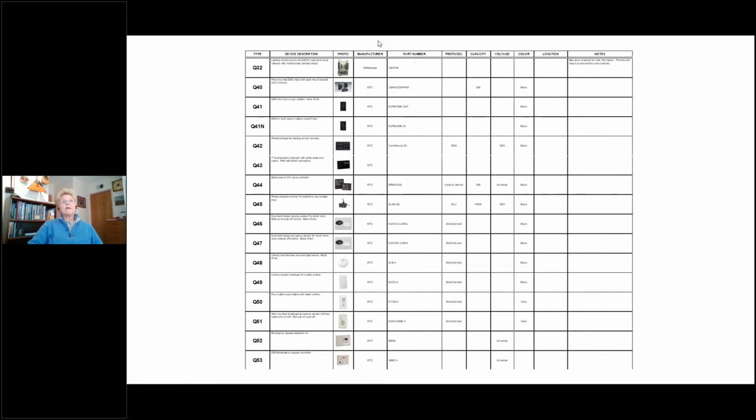So one of the ways that I make this simple for people is I develop a schedule for all of the devices. So as you noted on the plan view, every one of the devices has a number and it has a device tag, just like a luminaire would have a tag. So whatever system you use, I just lump all of mine into the letter Q. Makes it simple that if it starts with a Q, then I know it has to be a control device.